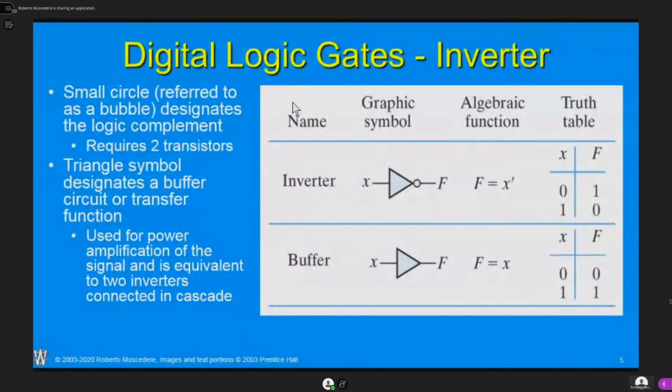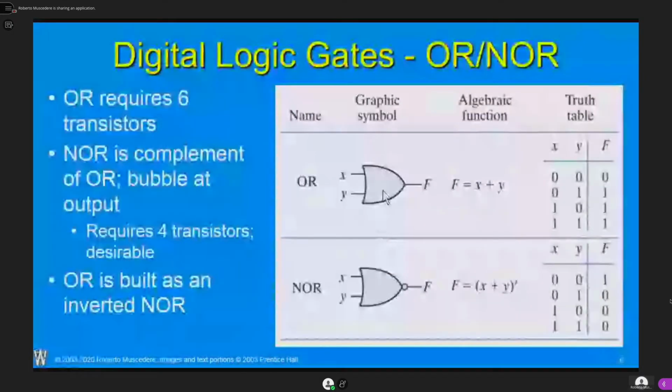If I put in a buffer, the circuit gets bigger. So we're always trying to build our circuit with the smallest physical gates possible and only put in larger buffer circuits when we need to. And again, that's what the software does for us. Because if I start putting in just arbitrary buffers all over the place, my circuit's going to get bigger and I don't have room for other things. And that's one of our limitations.